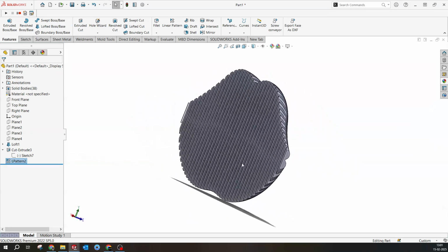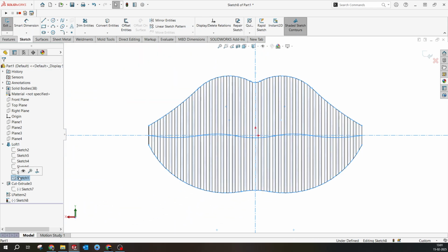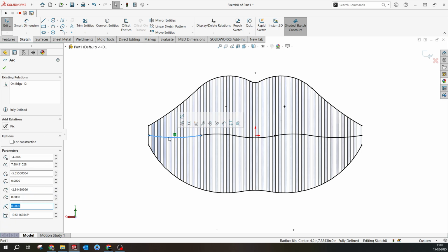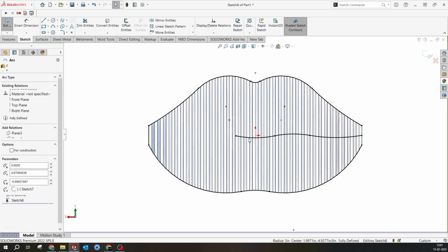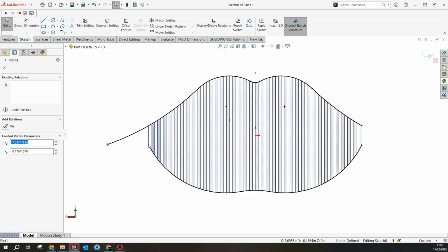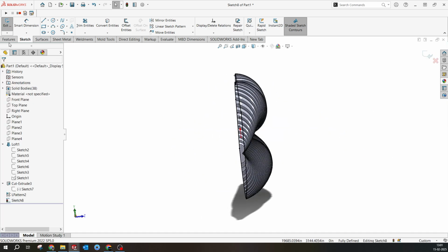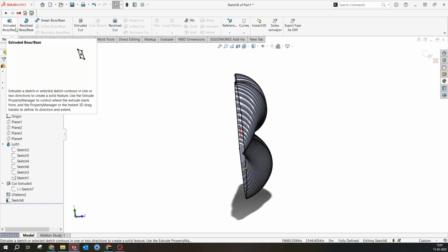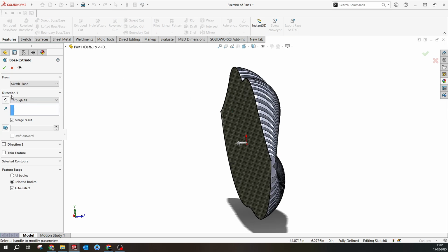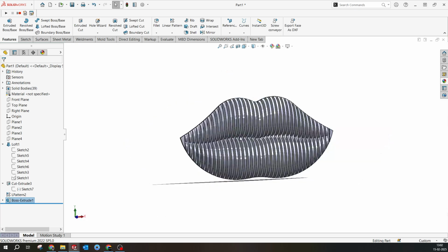In order to mount, you have to watch my previous video, so it will be easy for you guys to see how to mount. This time I will be removing all these single or center entities. I will be making this a connecting point. I will be trimming again. So this is my base to connect the plate. Same 0.15. Don't merge with the profile. Yes, perfect.